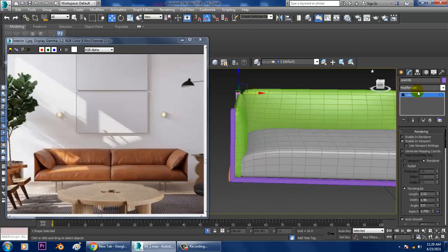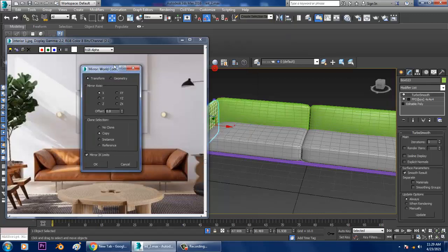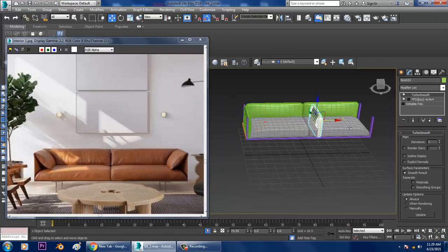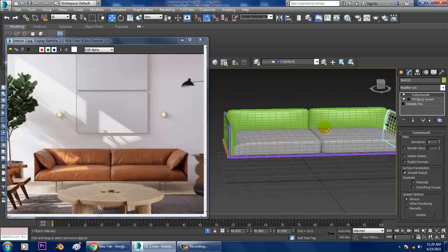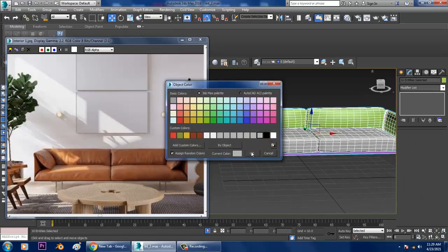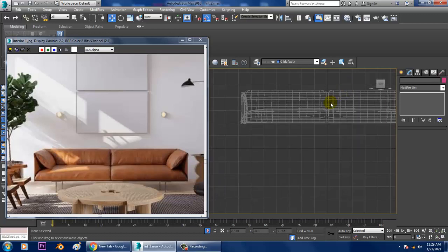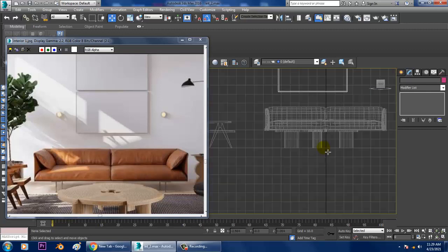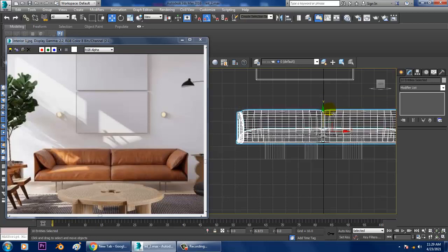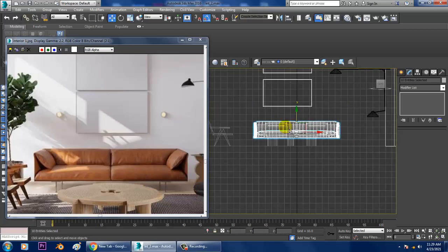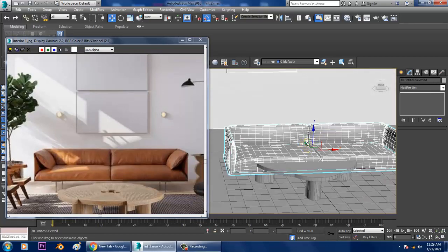So select this. So again duplicate this, mirror it in x-axis, make a copy of it in the right direction. That's it. So select this and just give one color to it. After that I'll just isolate this over here, select this, exclude it, slightly shuffle it down over here. So make sure you are shuffling this behind.